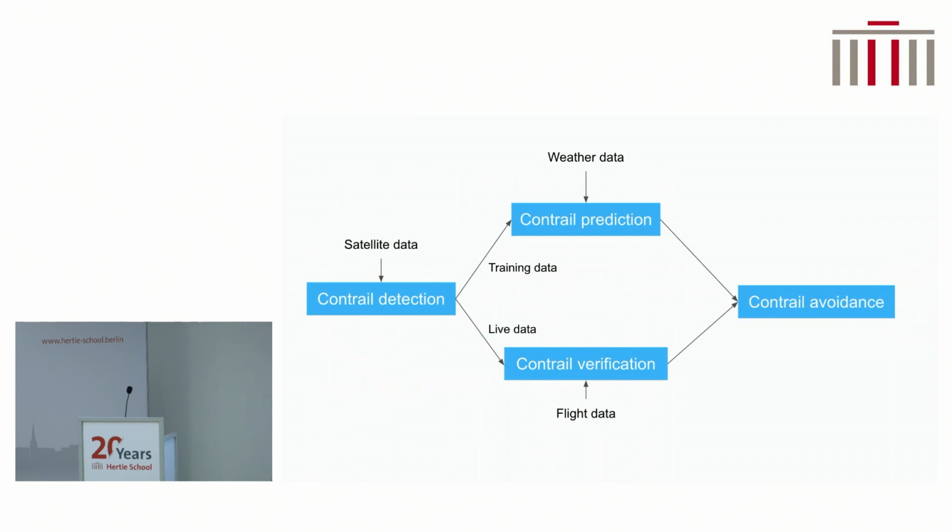So what do you need to help them? You need two things fundamentally. First, as I was alluding to, you need contrail prediction. So what we do is we take the weather data from the ECMWF, which is the European medium-range, long-range weather predictions. I can get into it if you would like to know more. Those are actually slightly biased and not quite right when it comes to humidity up by the stratosphere. So we have to fix it up with machine learning. But we built a contrail predictor to predict these regions, which we call contrail likely zones.